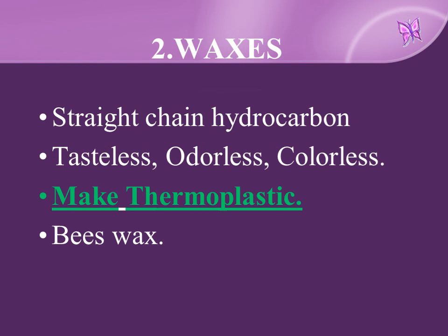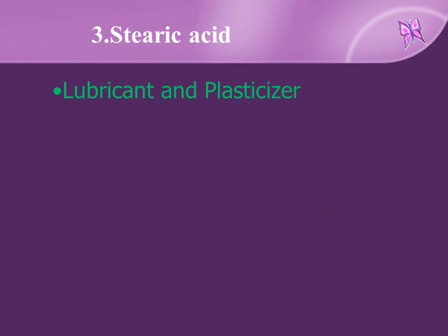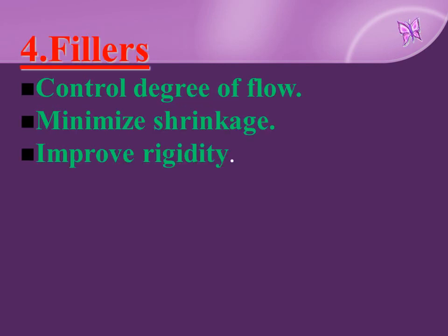Straight chain hydrocarbon: tasteless, odorless, colorless, make thermoplastic, like beeswax. Stearic acid: lubricant and plasticizer. Fillers: control degree of flow, minimize shrinkage, improve rigidity.